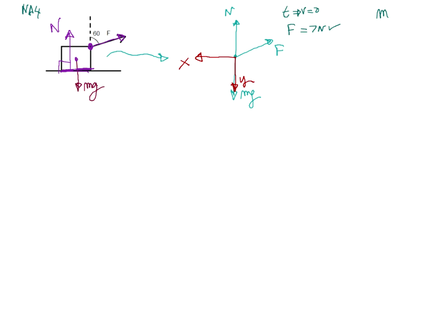Based on this free body diagram, we know not only that it's horizontal, but we also know for sure in which direction along the horizontal. Left or right? Right. Excellent. Which means that acceleration is that way. Exactly. Now, an acceleration should never be part of your free body diagram. That always messes people up, so I put it on the side.